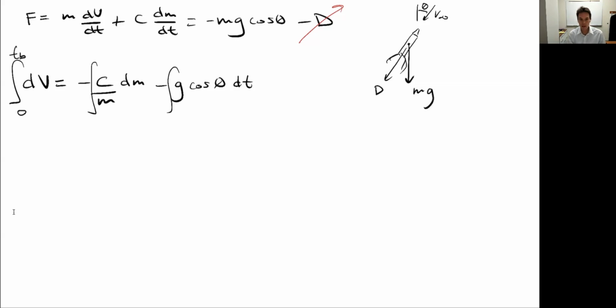Ideally, this is where I would do a numerical integration, because some of these terms are going to change, but for purposes of getting a rough equation to see how these factors contribute, we're going to assume some things are constant. On this side, this just becomes delta V. This is how does my velocity change? It's 0 at the beginning. What is it at the end? And it may not be 0. I may be looking at a second stage of the rocket where I start from already some speed. But anyway, this is how much my velocity changes.